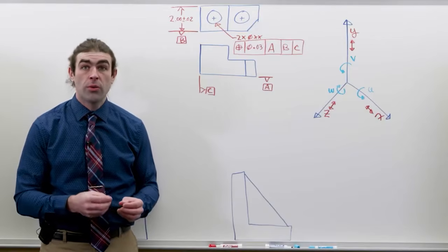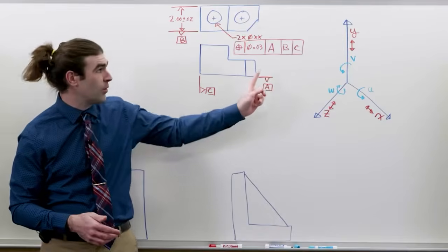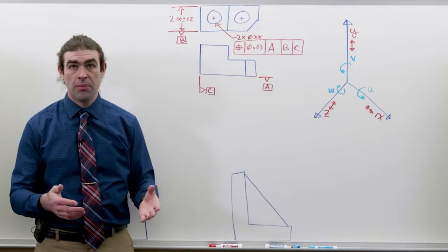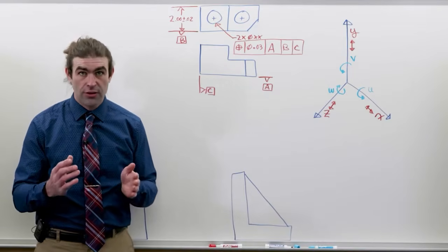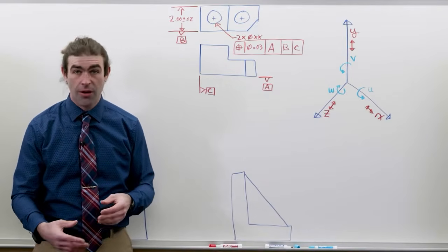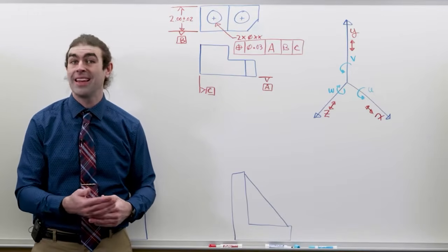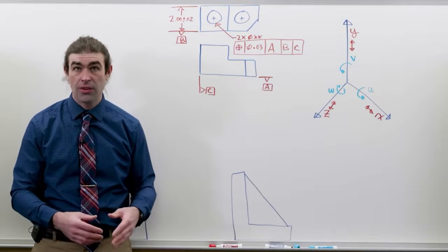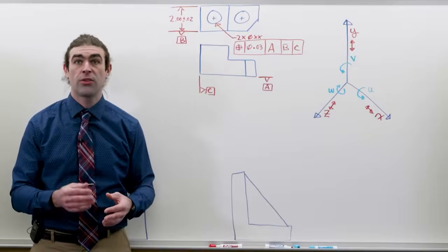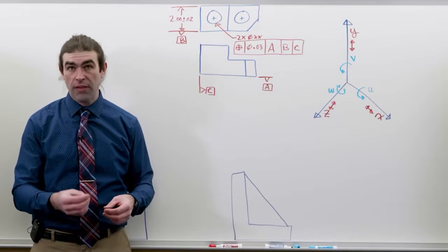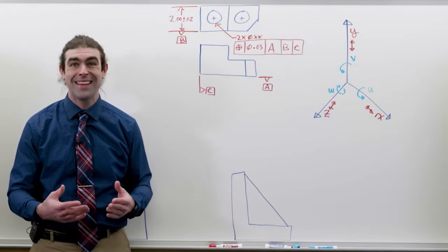One thing I want to mention when we do use the MMC, so what it's known as when it's used as the datum reference is MMB, maximum material boundary. You can still check it as if it's RFS. That's totally fine. RFS is always a more stringent call out than MMC. So anything that says MMC, you check it as if it's RFS and it passes, you're good. It's only when the piece fails that you might need to go back and account for the MMC or the MMB.